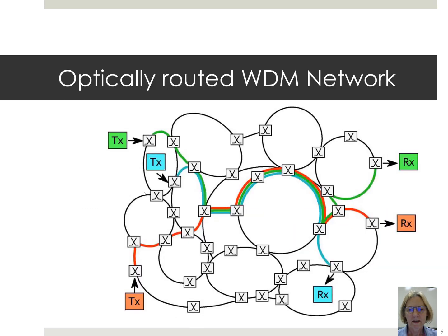So we have wavelength division multiplexing, and we use these in optical networks. What we'll see going on here is a description with different colors representing different wavelengths. Information could be routed from one transmitter to another receiver pair using the wavelength to choose the route along the network. And we can see these units, these switching units, which can read the headers and route the wavelength accordingly.